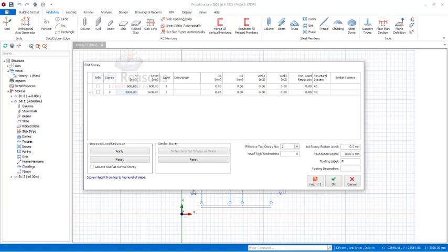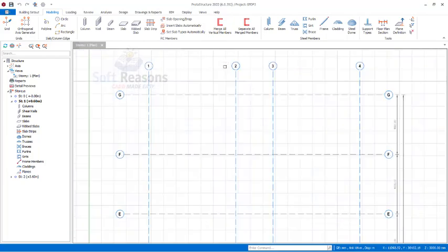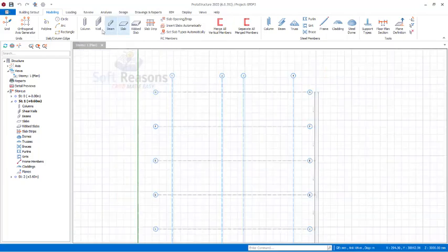After which, the next thing we will be considering is the structural system. For story 1, we'll be having it as RC, which is reinforced concrete. Then for story 2, we're having it as steel. This will make the program able to design effectively the structural members. So these are necessary settings. Click on OK, after which we straight away go to the reinforced concrete member, the columns.